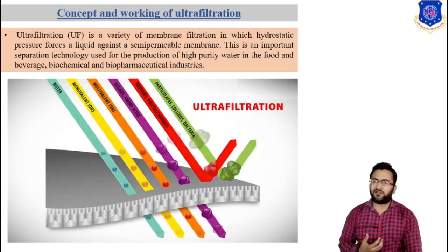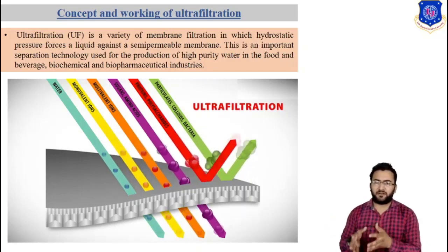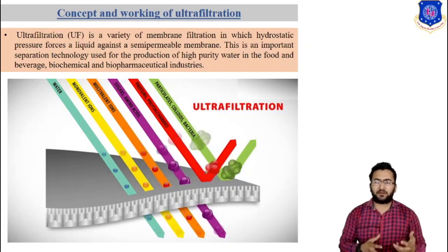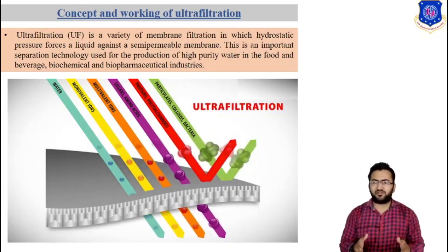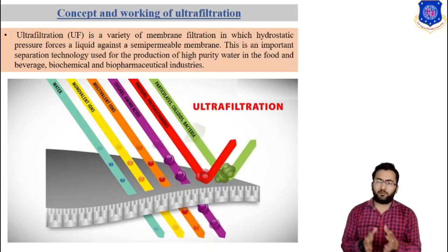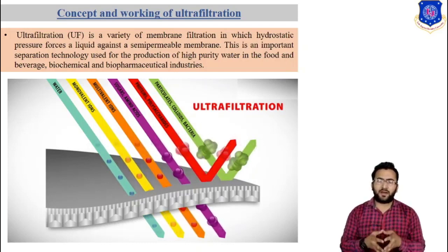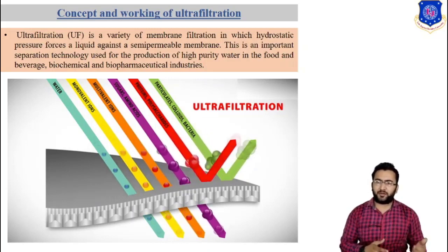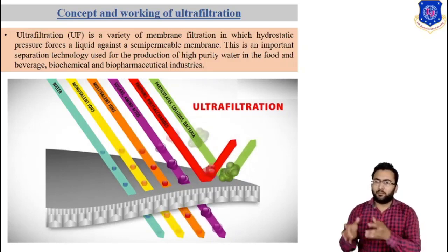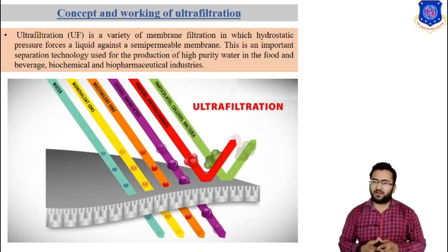The various membrane characteristics are used to understand the behavior of ultrafiltration membranes. The permeability of an ultrafiltration membrane is determined by the pore size, pore density, and thickness of the membrane active layer. Conventional methods of membrane characterization sometimes prove unsuitable for ultrafiltration membranes. Direct microscopic observation of the surface is difficult, and the pores, especially the smaller ones, get closed when samples are dried for electron microscopy. On the other hand, ultrafiltration membranes contain pores too small to test by the bubble point. So molecular weight cutoff is the most widely used method for the characterization of ultrafiltration membranes.